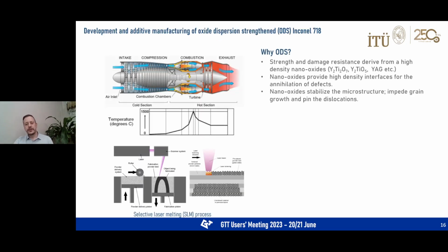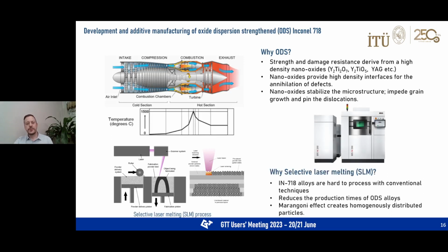As it is known, Inconel 718 has superior mechanical properties, thus it is widely used for elevated temperature applications such as gas turbines, turbocharger rotors, and nuclear reactors. However, above 700 degrees Celsius, a sudden decrease in mechanical properties of the alloy is reported in the literature due to the particle growth and lack of stability of the strengthening precipitates.